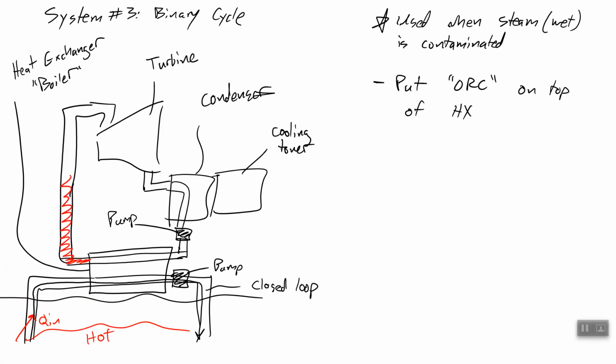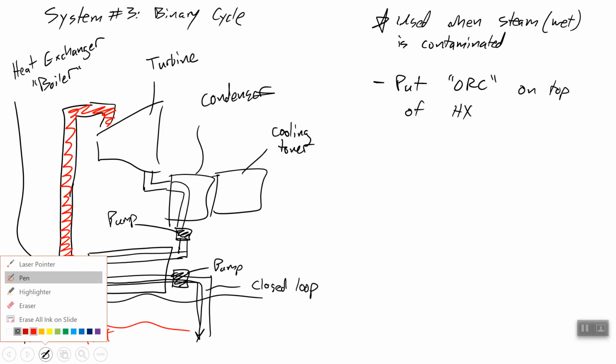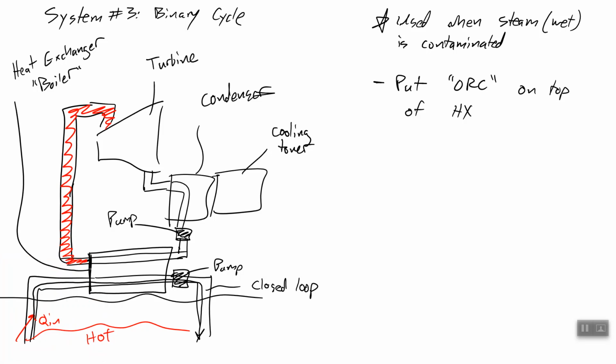So you see we have a closed loop here, and leaving this heat exchanger is going to be hot, high pressure steam that we evaporated here in this heat exchanger, the boiler. Then that steam expands in the turbine, dropping its pressure, becoming a saturated vapor here before that heat leaves and it's turned back into a liquid, transferring that heat into the working fluid of the cooling tower so that that heat is ultimately rejected as Q out.